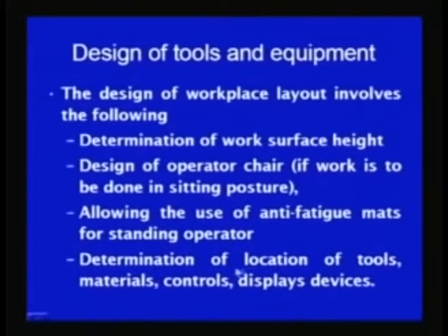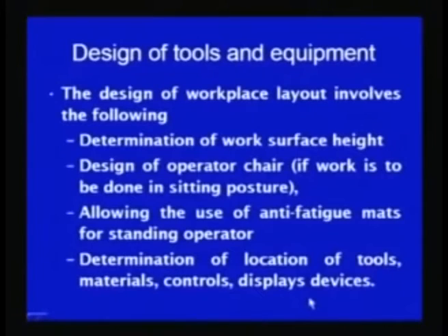The location of tools, materials, and control display devices should be determined in such a way that the operator can use the tools and materials with minimum effort and fatigue, and at the same time error-free and easy control is possible with the proper design and location of the control and display devices.